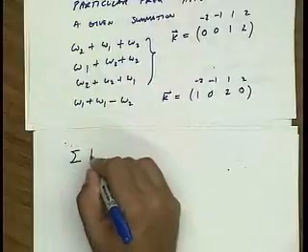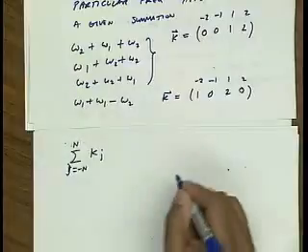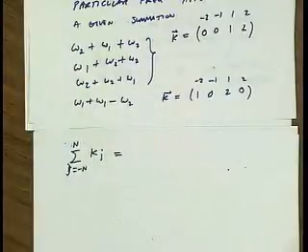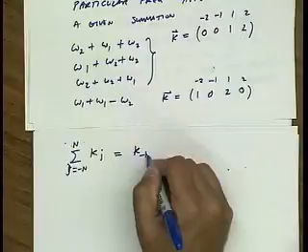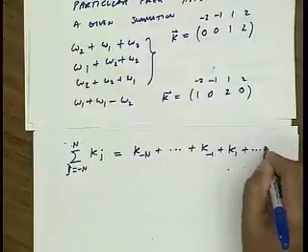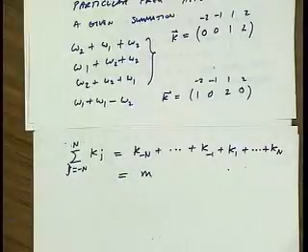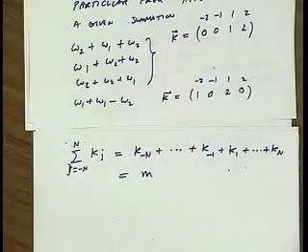Well, you'll also notice that for a particular mth order power, if I take the sum of kj, j goes from minus n to n, what do I get? M, exactly. So this is k minus n plus k minus 1, k1, all the way to kn, and that just has to sum up to m, right? I can't get more than m different frequencies. Okay? I can't get more than m non-distinct frequencies. All right, any questions up to here?